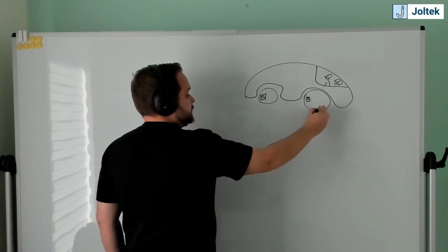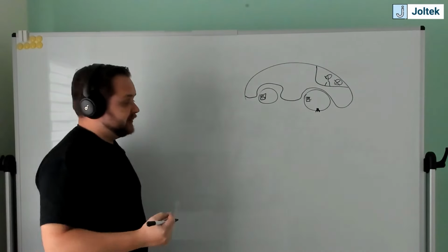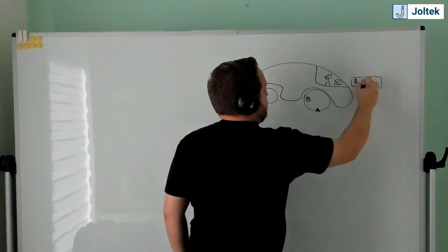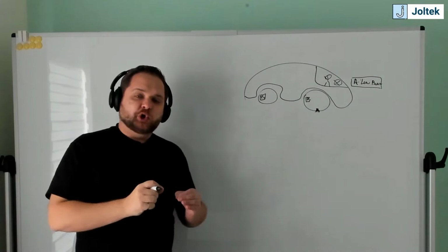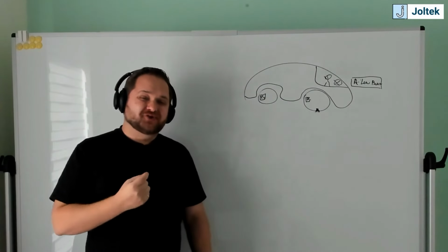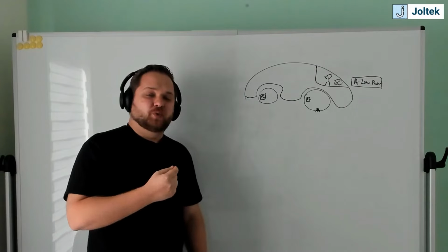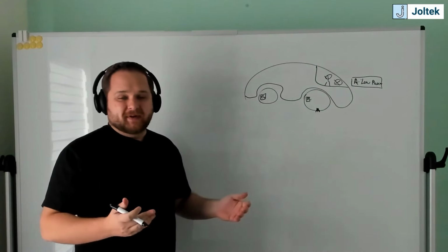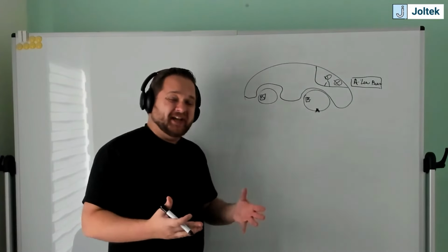Once you encounter a puncture, the tire is going to start deflating. Once it drops below a certain pressure level, you're going to have a warning. So here I have an alarm: low pressure. And so why is this important? This is important because who is that alarm destined for? So number one, it is an alarm upon which the driver needs to immediately act and pull over to make sure that there's no issue with the tire, which ultimately there is. So hopefully they pull over within the next couple of seconds, or hopefully minutes if they have a small enough leak, and they're able to change that tire.